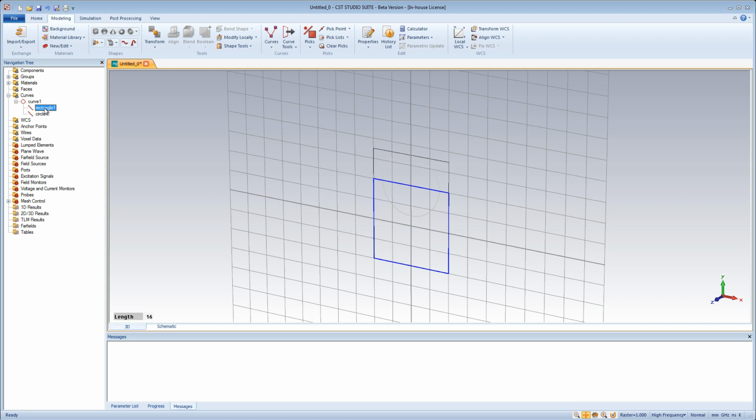Now trim both curve items so that the resulting curve contains only the outlines of both curve items. First select one of the curve items, here Rectangle 1. Afterward, activate the Trim Curves operation by choosing Curve Tools, Trim Curves. You will be prompted to select the item to be trimmed with the rectangle. Select the circle and confirm your selection by pressing the return key.